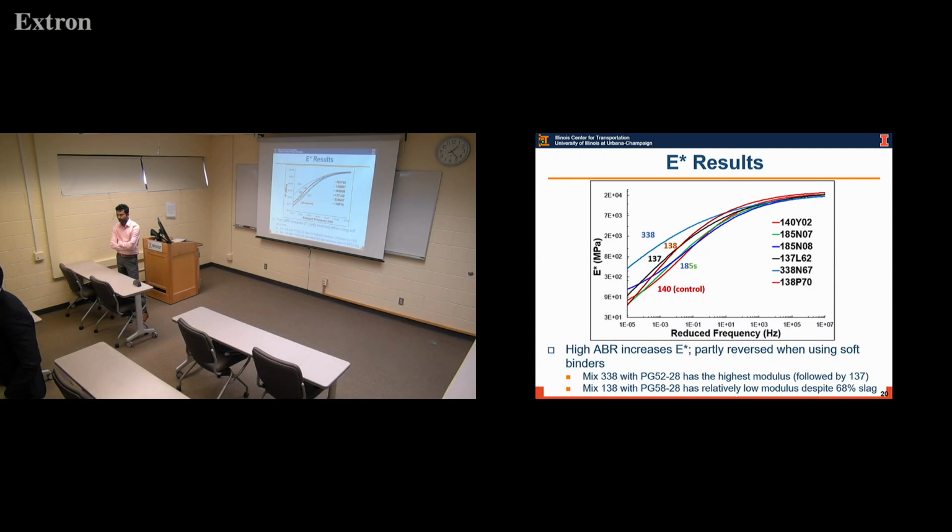What we basically did to evaluate that part was the following. When you do DIC, you paint the specimen. So we take a picture of the specimen before the painting, and we put some control points. When we have the painting, we can correlate that strain field over the picture before the painting, and that's the picture I show in all my slides with the setup, where you have seen the aggregate. That's how we evaluate that most of the fracture processing, and I'm very confident more than 90% is binder. This is mostly mastic that is failing.